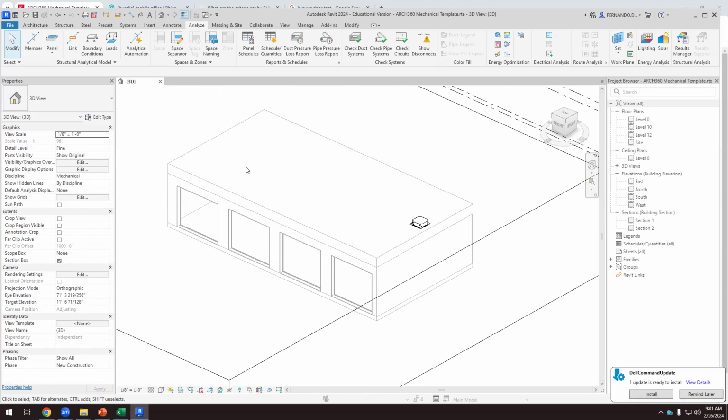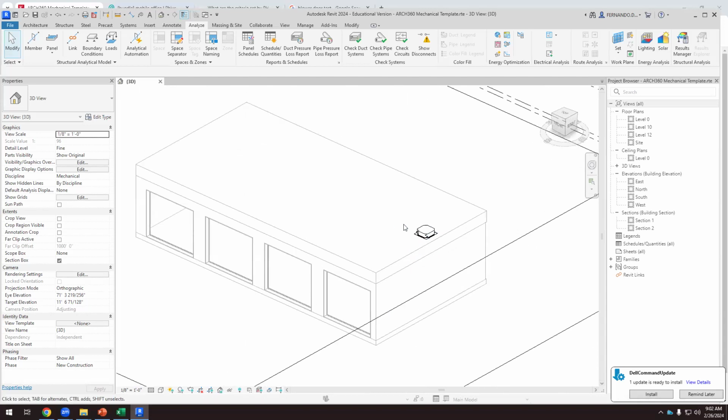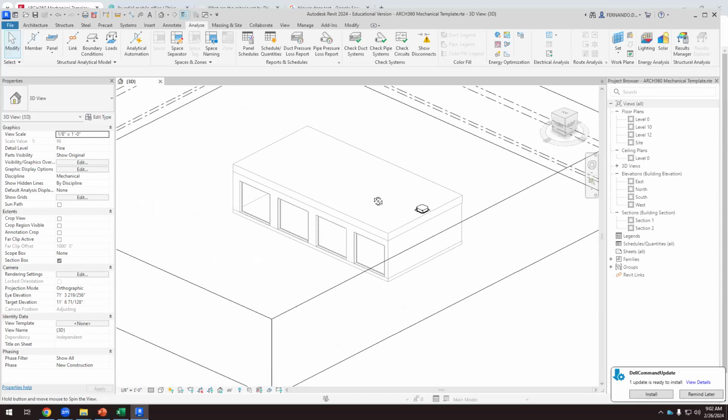here we don't have any spaces. So you need to work with two different files on the same building. One simplified file just to analyze the spaces and the thermal performance. And if we want to do anything else, if we want to work with the structural, with the mechanical or whatever, we need a different file. Because usually if we connect everything in the same file, the energy simulation doesn't work well. So that's why I'm using something different here.